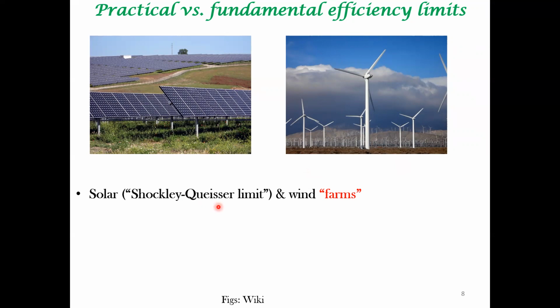So this depends upon the input energy, which is the black body radiation of the sun, and the output power depends upon the band gap of a semiconductor. I think Shockley and Queisser analyzed this for the first time for silicon, I guess. So there's a bound beyond which we cannot go. So it is very important to have a conceptual analysis of what the bounds of energy conversion are, for example, solar energy to power output from a solar cell.